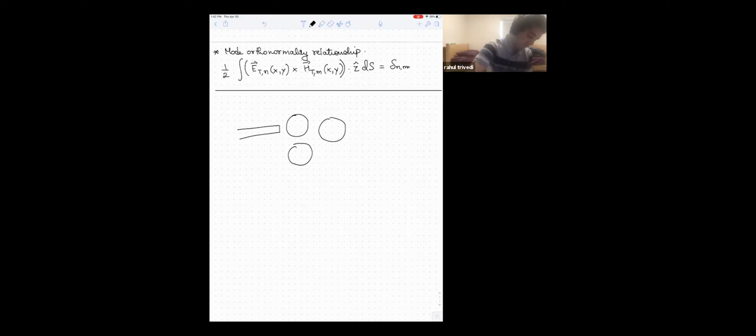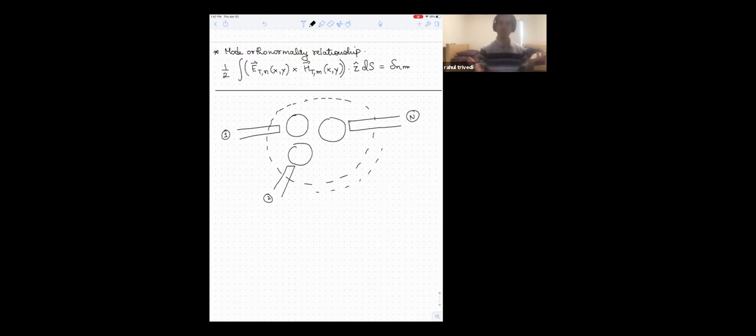And these cavities are being fed with inputs through some waveguides, right? So there are waveguides that are going towards the cavity, and then there are waveguides that are coming out of the cavity, right? So at a very general level, you can think of this device as a waveguide-based device, right? If you just black box this permittivity distribution and not really think about what's happening inside for the time being, what you essentially have is an n-port waveguide device, right? So assuming this is waveguide 1, waveguide 2, waveguide n, you have an n-port waveguide-based device, right?